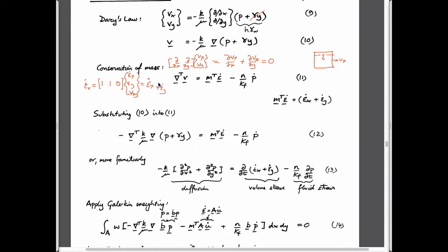The opposite is to keep the boundary of the system open and now change the fluid pressure. If you have a can full of something and you increase the fluid pressure, then the volume of the fluid decreases, so it gets smaller inside the can. The can stays the same volume, and so you have to supply some fluid into it to fill up that extra space that you're making. And so the volume change due to the fluid straining would be the pressure change in the fluid multiplied by 1 over the stiffness, which is the compressibility.